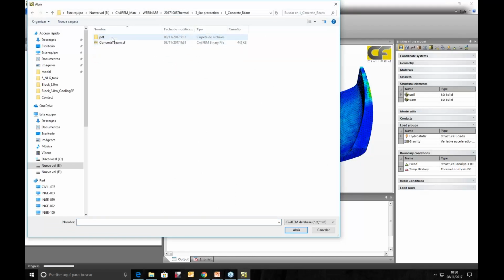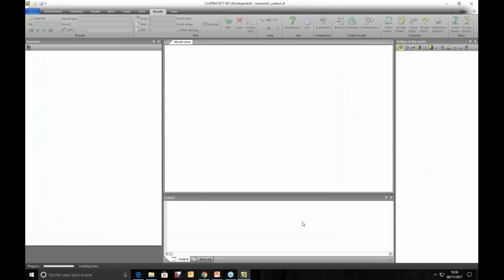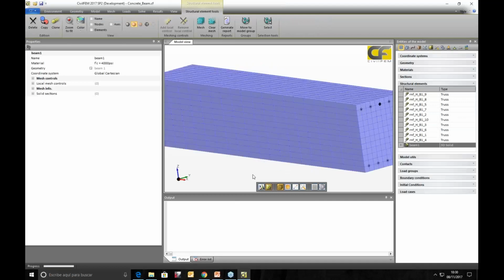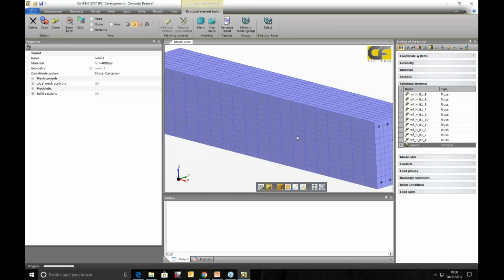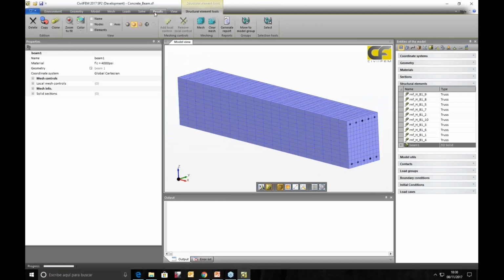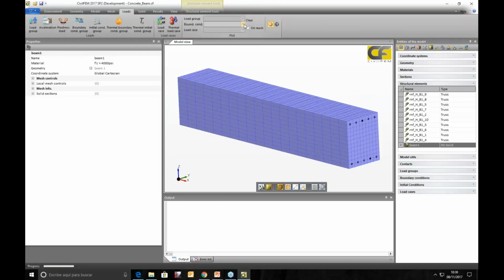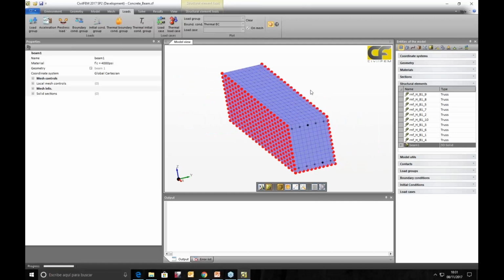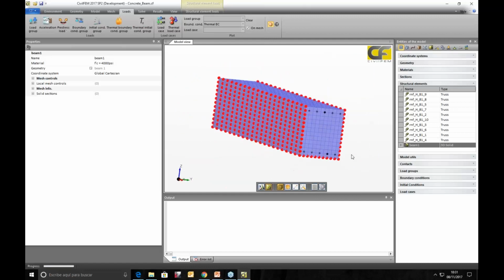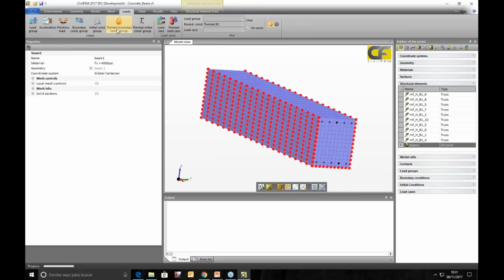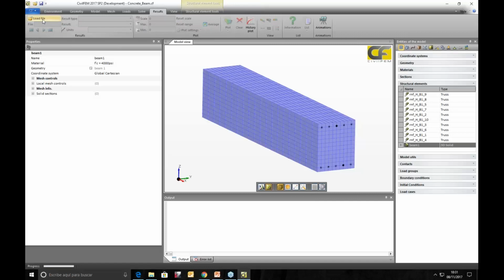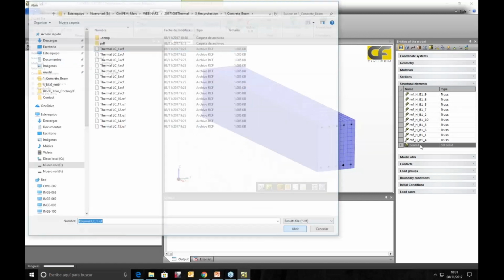Here fire protection, concrete beam, and if we open it, we can see the results. Here is a concrete beam. We have the reinforcement and the concrete, and here we apply the boundary conditions. We plotted the thermal boundary conditions: there is a fire around it, not on top, because this is holding a slab, and we suppose there is no thermal heating there, but around it. And we have solved, in this case, the transient thermal analysis, and we can see the results here. Now, plotted.